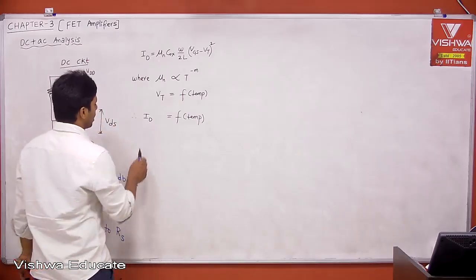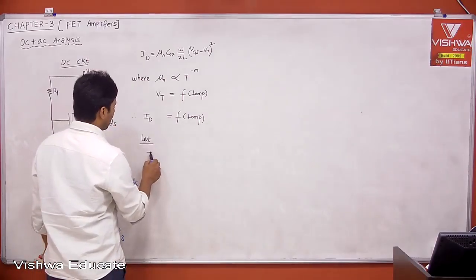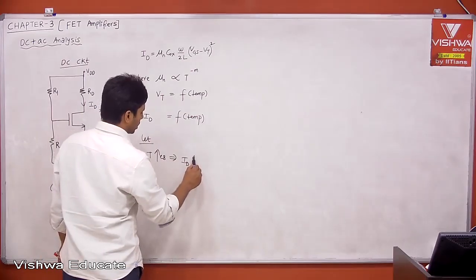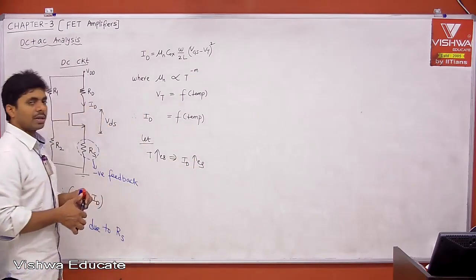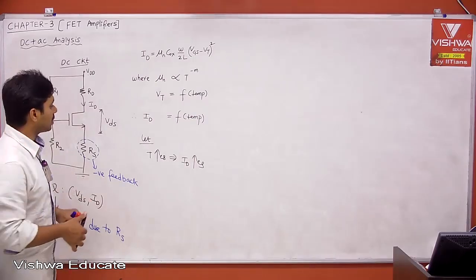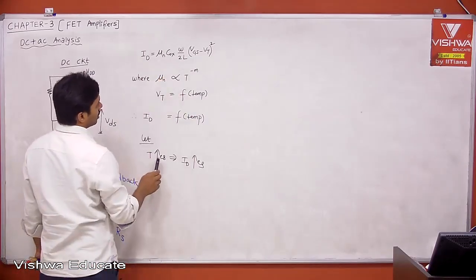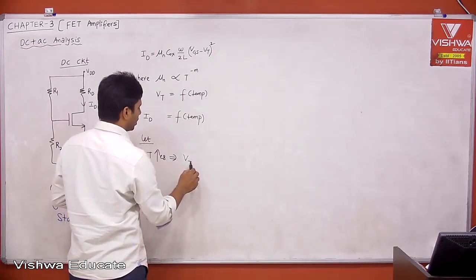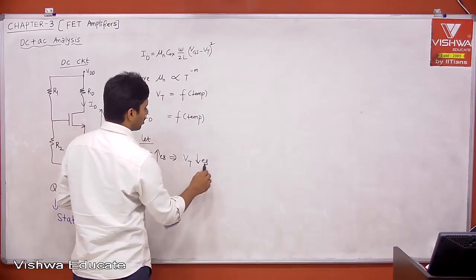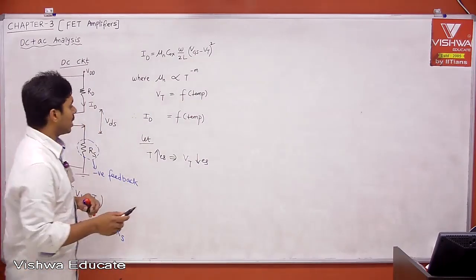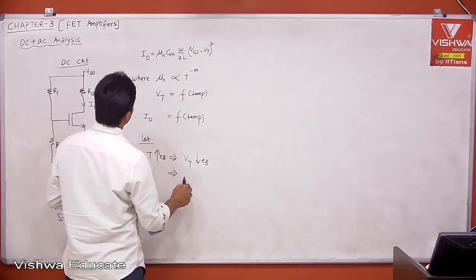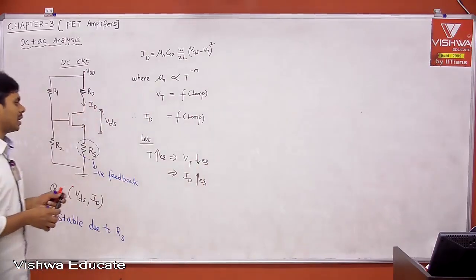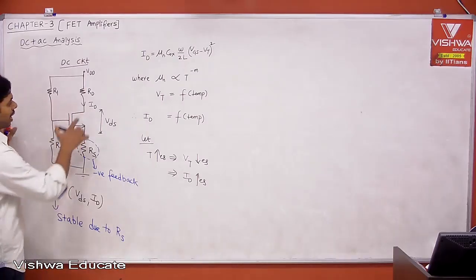Therefore, in older technology, if temperature increases, typically ID increases. Typically. Therefore, at higher temperature it is faster. That is with respect to threshold voltage. When temperature increases, VT decreases, so the amount of gate to source voltage required to form the channel decreases. If VT is decreasing, overall your ID increases. That is what is dominating. Therefore, if temperature increases, your ID is increasing.